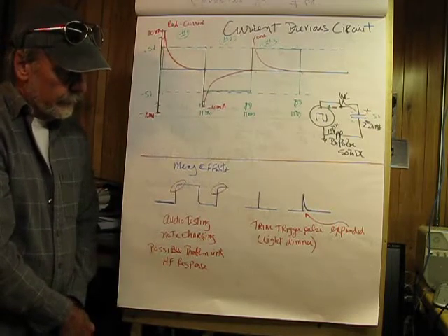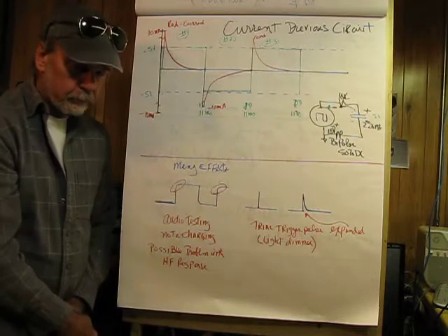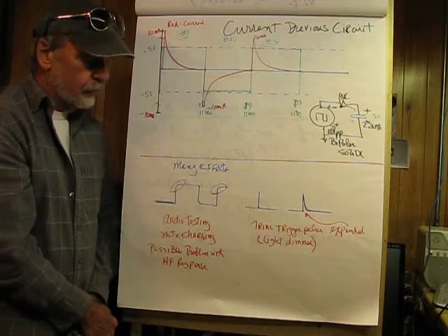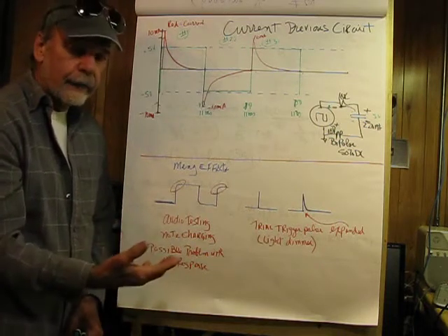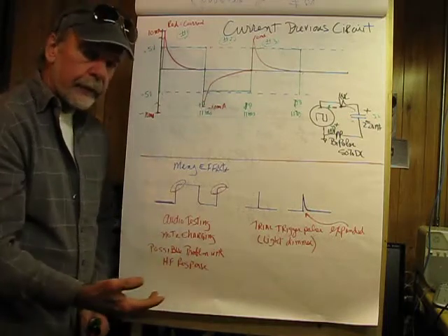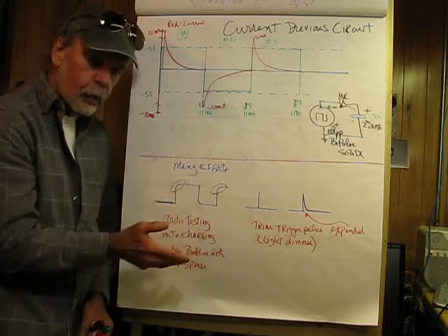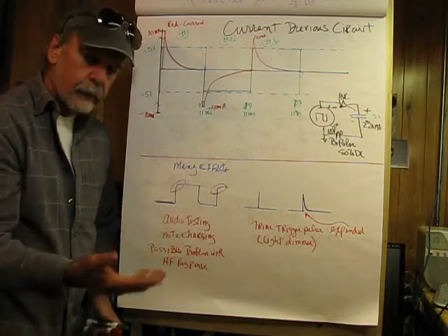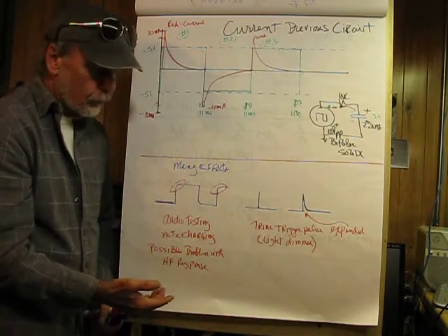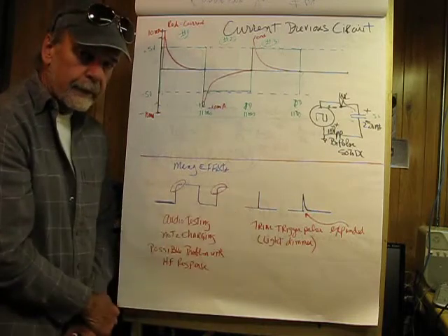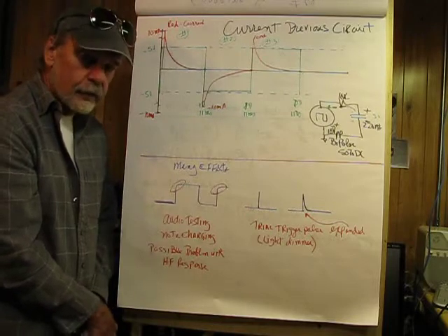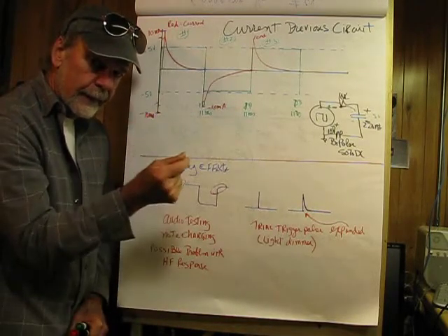And in a triac circuit, like a light dimmer, we trigger the triac at certain periods of time relative to 60 Hertz, and that turns on the triac and turns on the light at different times. Now what's important in a triac, which is an AC control device, kind of like a transistor in general terms, is that we turn it on hard and fast. So this would be the pulse that's applied to the gate. And this is like getting punched in the face. It's a lot of energy delivered into the triac, so it turns on now.